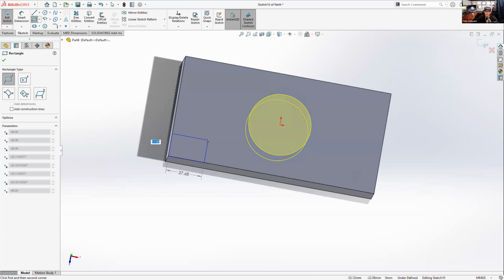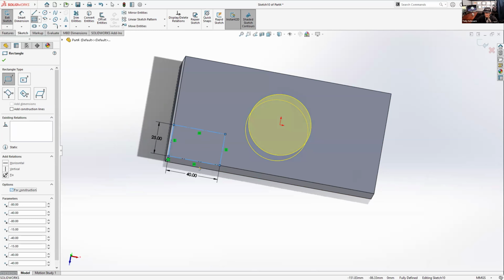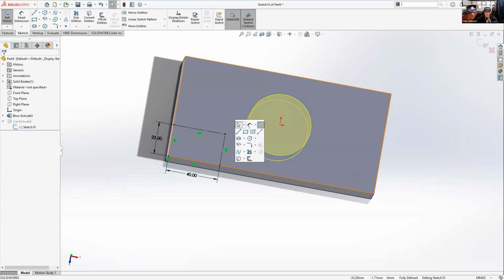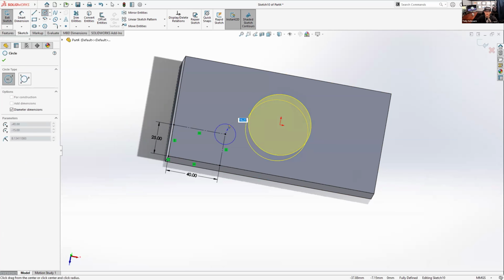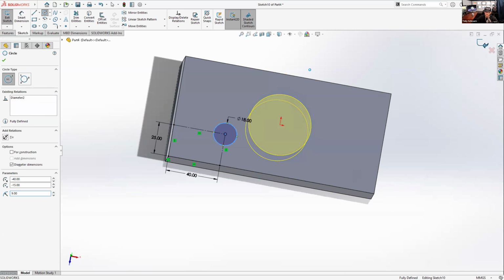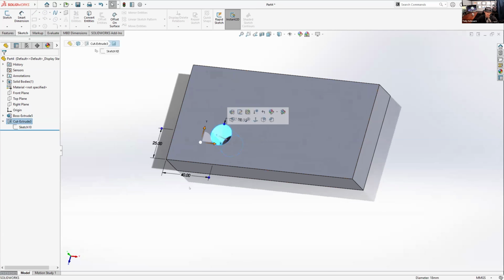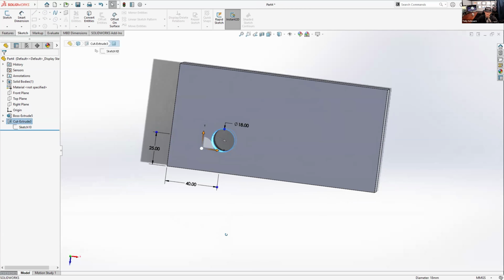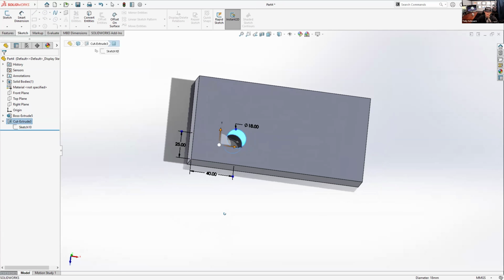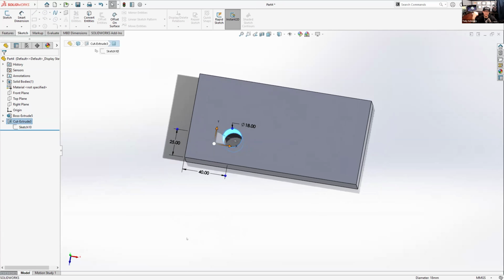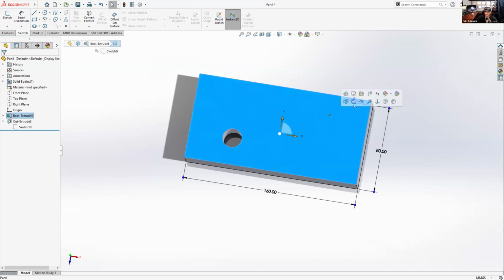So you know where that circle's supposed to be, so you type in 25, 40 for construction because it's already highlighted, and then S key circle, and then 18 millimeters, and now you've got your hole there, which is now parametrically defined. Not like you did anything wrong before. You were able to locate it using a different workflow. I think it's a really clever workflow, instead of doing it with a regular 2-dimension location for that hole.